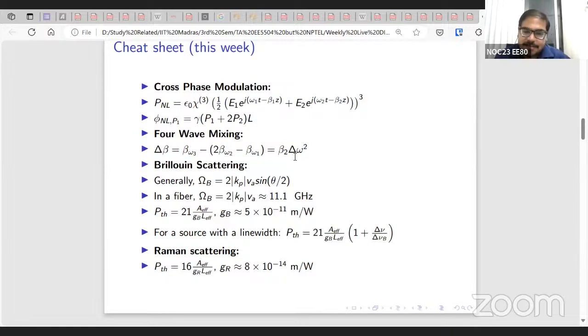And then we talked about Rayleigh scattering, like what kind of frequencies you can expect in free space or in some fluid, and what kind of values you can expect in optical fiber. So you will have peaks offset by this much from where you're sending your signal.